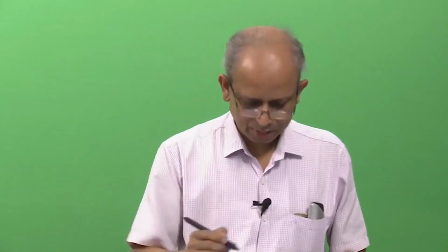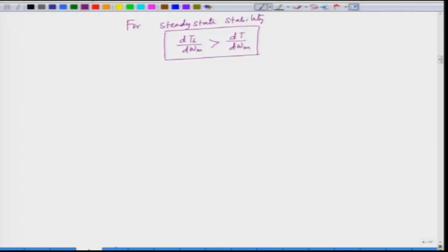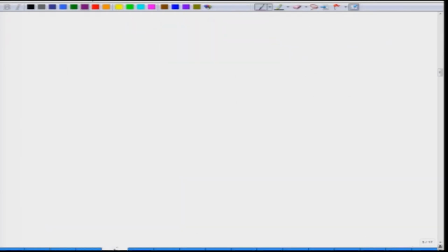Now, let us go further and we will discuss what is called load equalization. Now, what do we mean by load equalization? We have various types of load, as we have already seen: we can have a fan type of load, a traction load, a constant power load. Now, we have some special loads which are pulsating in nature. The load torque does not remain constant, it changes with time and goes up and down.